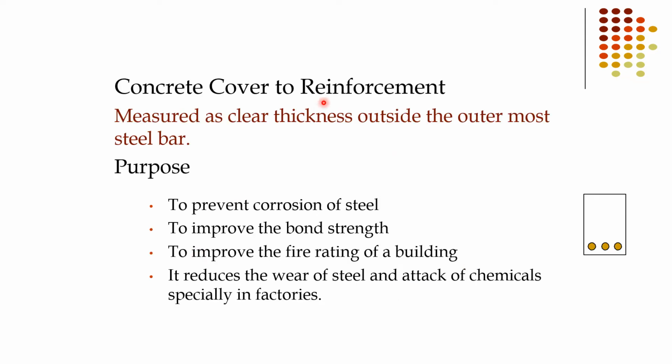Concrete cover to reinforcement, that is also very important. When we provide the reinforcement, we also provide the concrete cover. Why do we provide it? To prevent corrosion of steel. If we provide the cover, then it will definitely protect the steel from corrosion. To improve the bond strength, definitely. If the concrete is present around the bars, then it develops a strong bond between the steel and concrete.